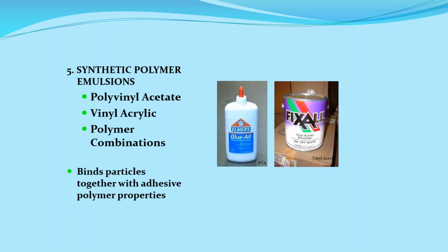And you'll see a lot of those types of applications in roadways that have a real high sand content, a real low clay content. They prefer not to deal with the clay, but they'll try and glue that material together. And so you're going to have to mix up the roadway and fluff it up, and then you apply the synthetic polymer emulsion. You mix it all up, you grade it back out, you lay it back down, you compact it, you let it dry, and it gets hard.